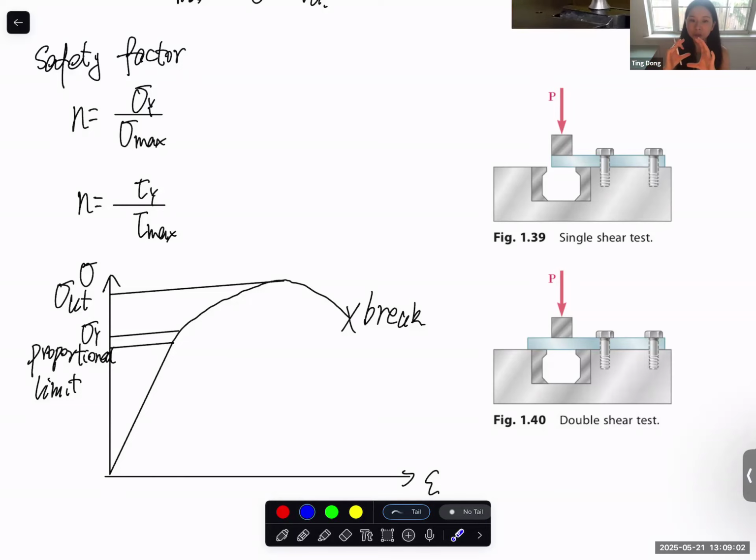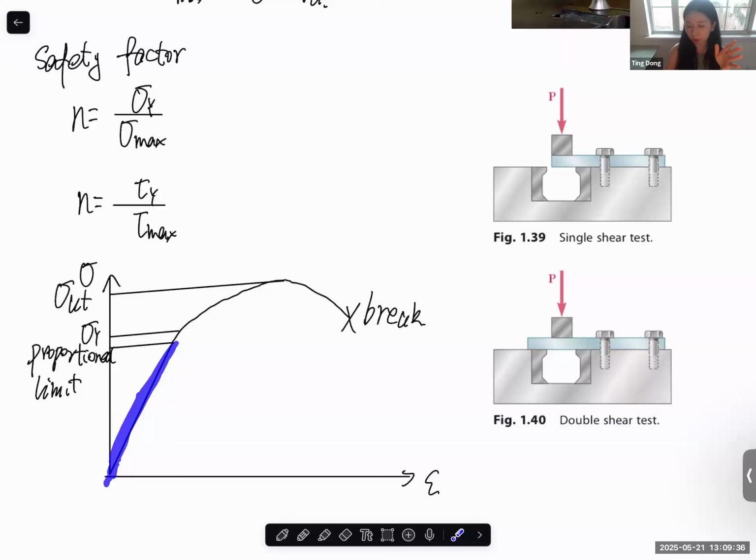And this pressure difference will generate stress on the fuselage structure. After flight, when your aircraft goes back to the ground, the inside and outside pressure are both at sea level. So this pressure difference becomes zero and the stress will go back to zero. Basically, during flight, stress increases, strain increases; back on the ground, stress goes back to zero, strain goes back to zero. And if everything is in the linear range, it's elastic deformation, everything should be fine.